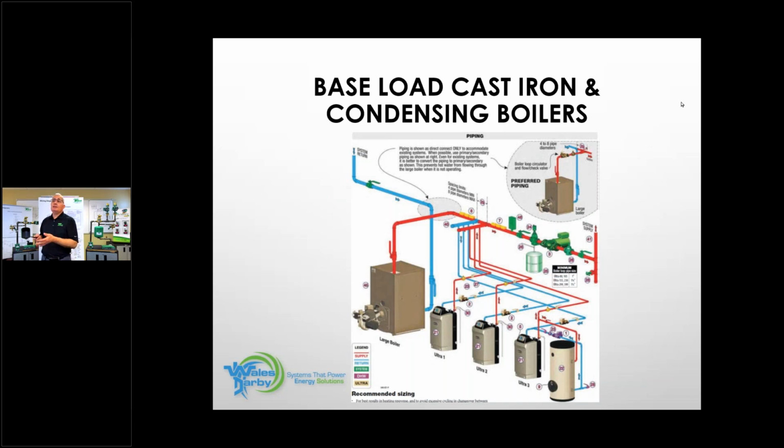And let's say this was a school or a municipal building. I was firing a big boiler plant in order to make domestic hot water. If I'm just taking care of sinks, I could just put an indirect on there and prioritize that zone. All right. So something to think about if you're walking into a project like this that maybe you thought wasn't within your wheelhouse, wasn't in your comfort zone.